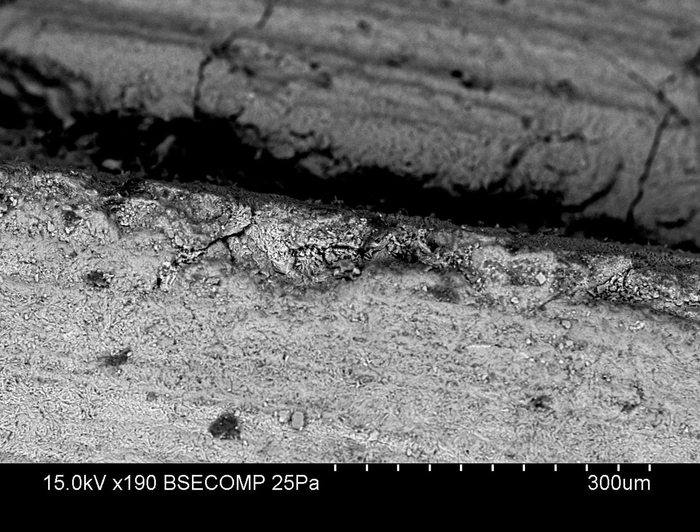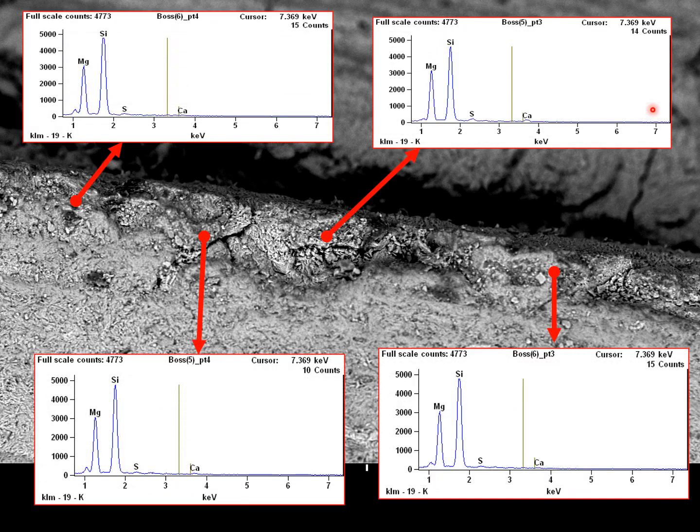In this backscatter electron image, the surface layer here is quite distinct from the underlying area of solid steatite. You can notice the loose platy structure. This is the enstatite cristobalite that is adhering to the surface of the carved seal. EDS points were taken at 3 different locations, and in each one the material is simply recorded as magnesium silicate, which it would be if it was just enstatite cristobalite.